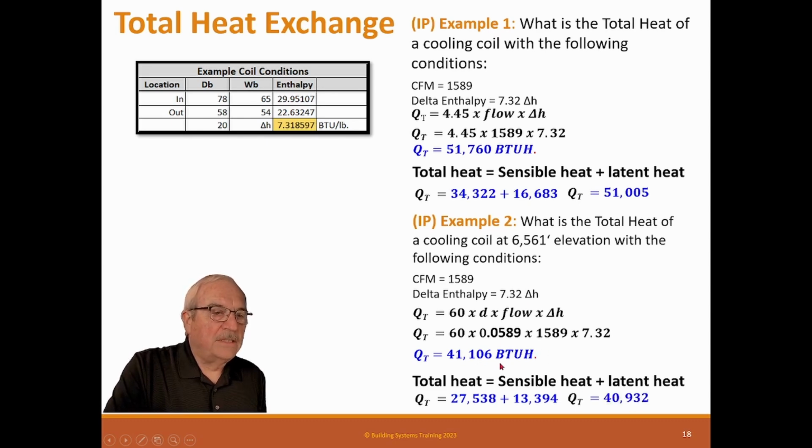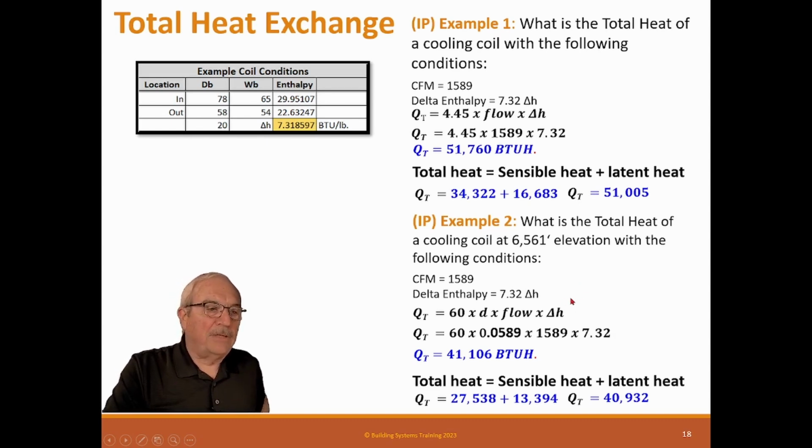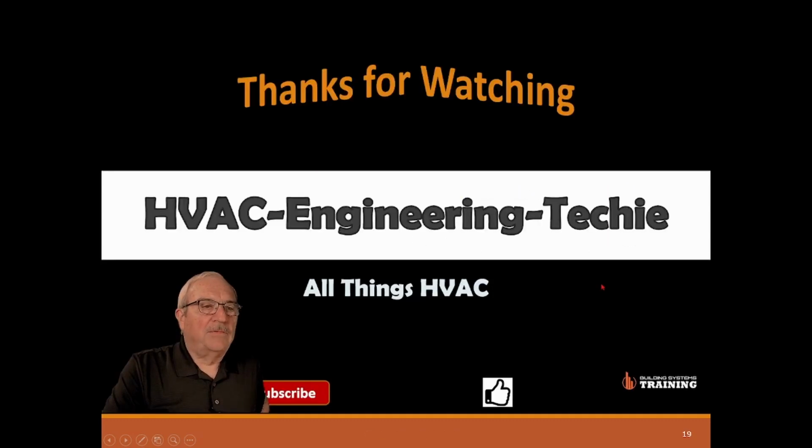So again, we have a few hundred BTU difference, but not too unreasonable to be able to affect the calculation. I've always, by just habit, because I have to know what the sensible heat is, I always calculate sensible, latent, and add them together. It's slightly higher than the total calc, but that's how I've always done it.